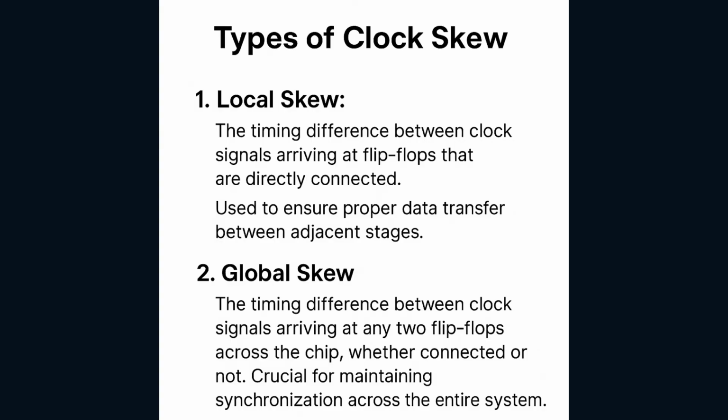Okay, so this difference, this skew, does the direction it goes matter? Like if the clock arrives later at the second flip-flop versus earlier, can skew sometimes be good? Or is it always bad news? That's a really sharp question. And yes, the direction matters immensely. Skews can be positive or negative, and it makes a huge difference to the circuit's timing.